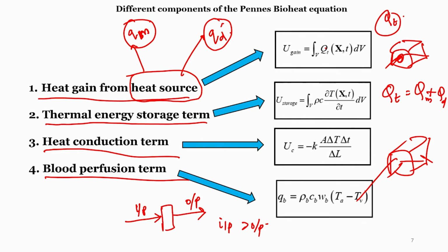What is that again? That will fundamentally mean m Cp dT only. The measure of that energy would be m Cp dT only, and if you want the power of it, we can divide it by time, dt. Power means we will get a rate of change of that stored energy as a function of time. So, what we do here is, rho is basically for the mass. Rho dV, we are integrating across the volume to get the mass.